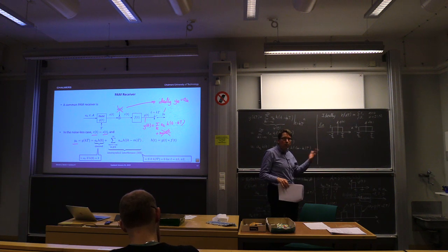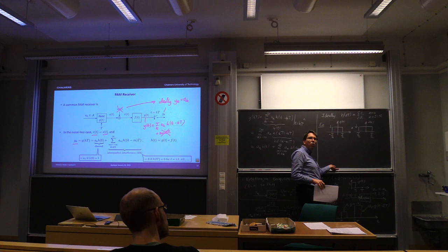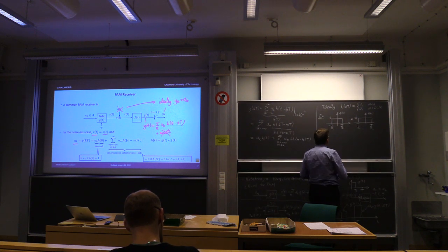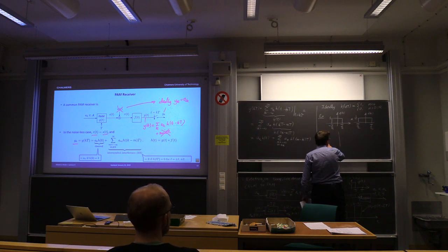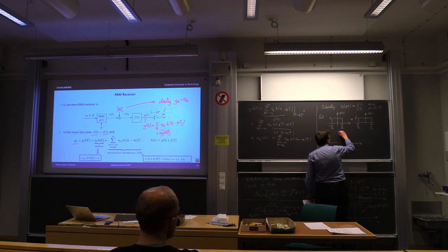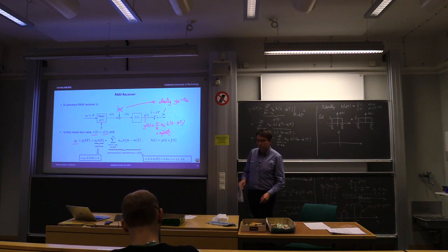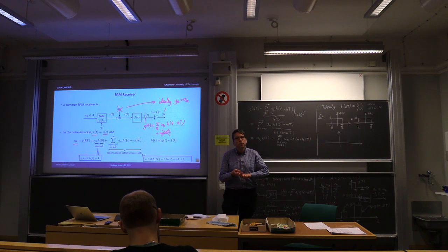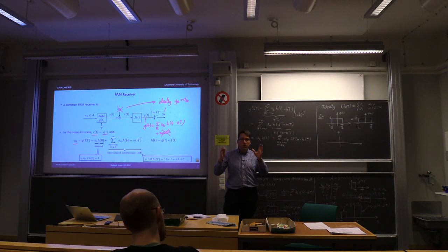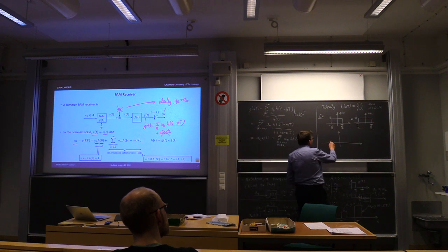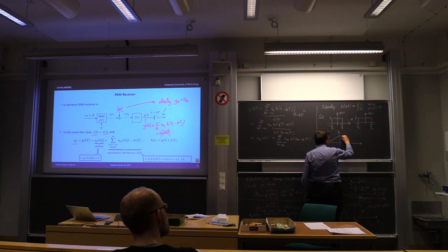Okay, and the amplitudes are not super important. The shapes are more important here. Okay, and if I convolve a box with a box, what do I get then? There are a few convolutions one should maybe memorize. So if I take a square pulse and I convolve it with itself, what do I get then? A triangular pulse, correct. So we will get a triangular pulse here.